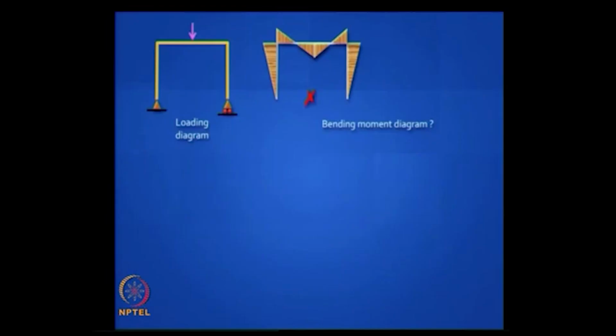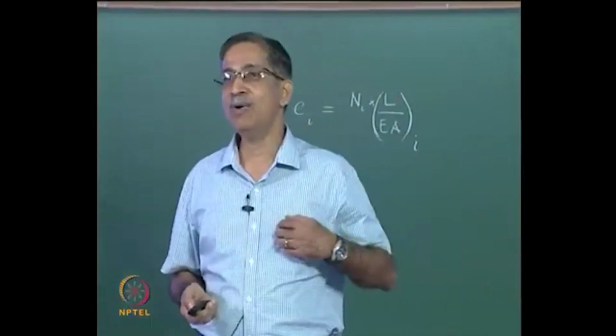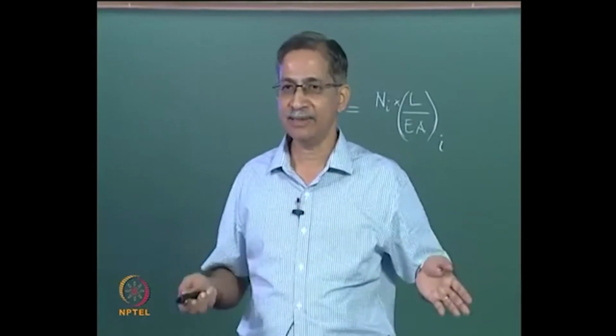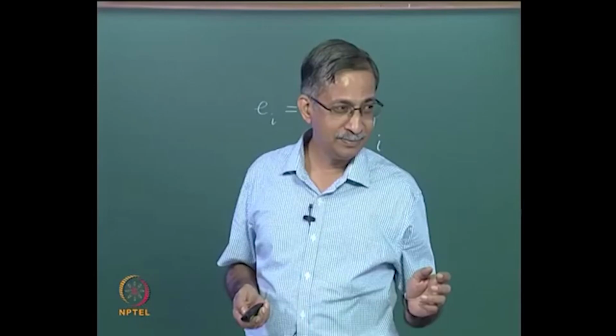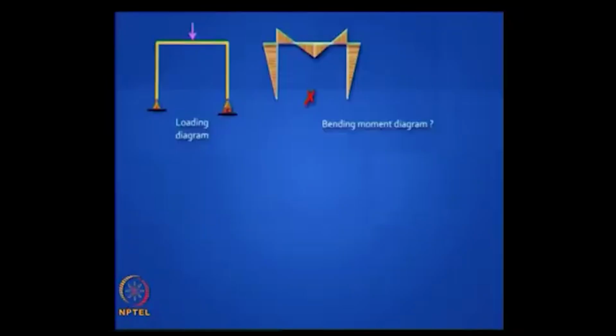Because in the vertical components there is no bending moment. Yeah, so there cannot be bending moments in the vertical components, that is the columns. Why not? Sir, only axial loads are there. No. Why only axial load? Sir, because only vertical reactions are there and no horizontal. No horizontal reaction. You see, you can't have a horizontal reaction at the supports in a simply supported beam subject to only vertical loading. So if the horizontal reaction is not there, you can't get a bending moment in that vertical element. So this is wrong.